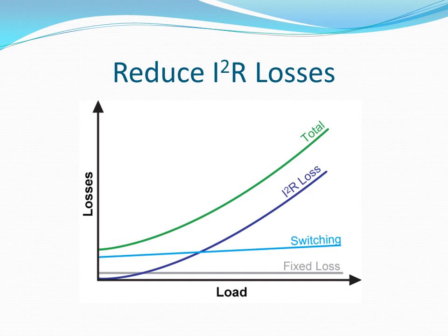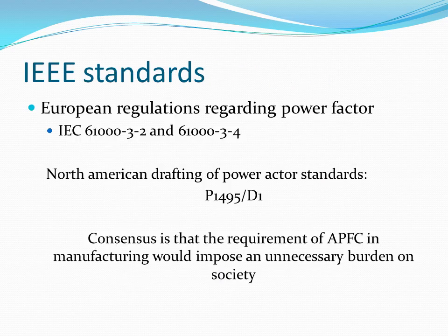When an induction motor, which is the most widely spread contributor to reactive power in a plant, needs reactive power, it is not necessary to draw it from the generators in the transmission grid, but a capacitor near the motor terminals can supply it. This relieves the generator and all transmission lines between the generator and the motor of having to transmit those VARs. Hence, the current in the lines will be smaller when the capacitor is installed. This will reduce the heat loss, or I²R losses, and reduce the voltage drop in the system. This is good news for the consumer and the utility.